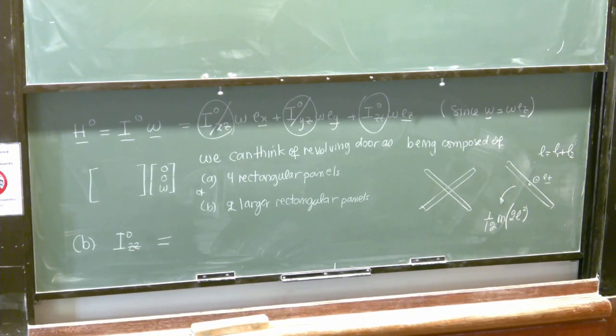So they will go away. Yeah, here you have total symmetry. So x equals 0, y equals 0, z equals 0 are all planes of symmetry. So there are many reasons why the products of inertia will cancel out here. Okay. Any other questions? Are we okay with this moment of inertia for each plate about its center?